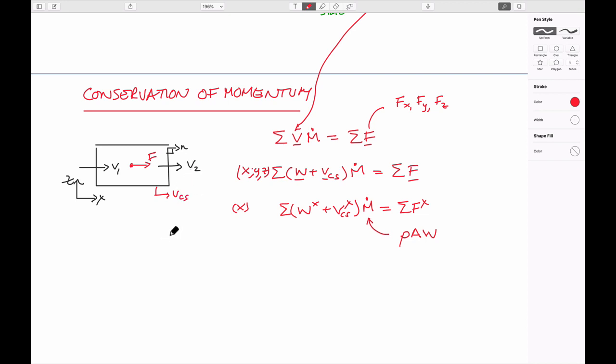And these would be static flow rates. And so we need to be able to make the distinction between relative to the boundary velocities and the velocity of the control surface. And so the sign convention for these, we have two components. We have a sign convention that goes in to define mass flow rates and one that defines velocities. These are always, importantly, relative to the coordinate directions, x, y, or z. Positive relative to these. And so in this particular case, if we are looking at mass flow rates, then because this is out of the volume, then this would be positive.